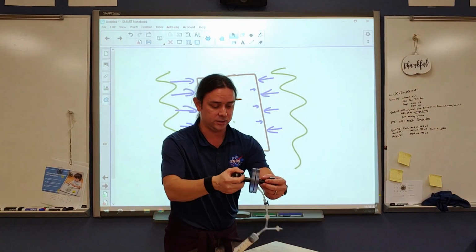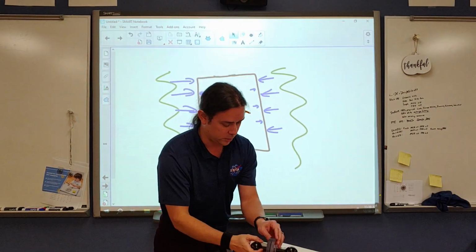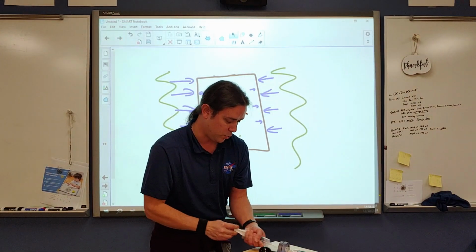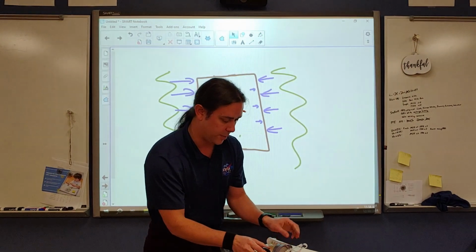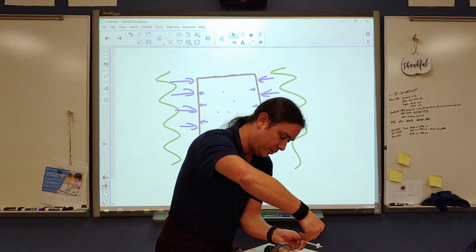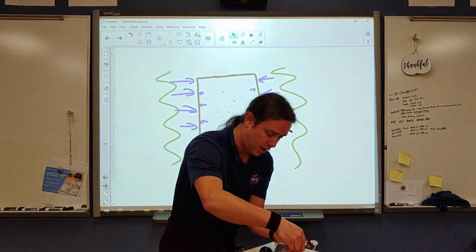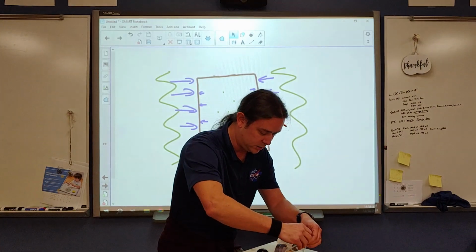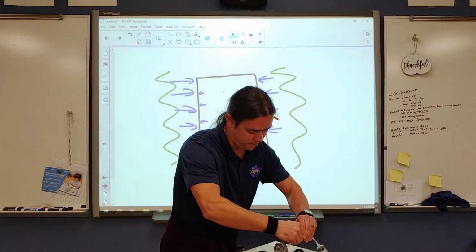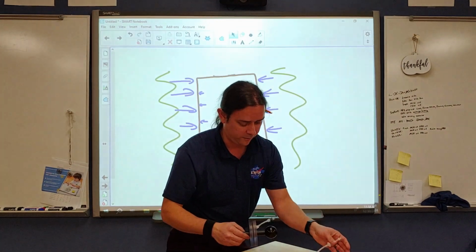So I'm going to really try and pull the air out. Now I'm doing this with a setup where I built in a couple things called check valves that actually seal this up. And then I'm going to change a valve here so that I can disconnect this. I've had problems with these breaking before because I didn't have a valve installed.